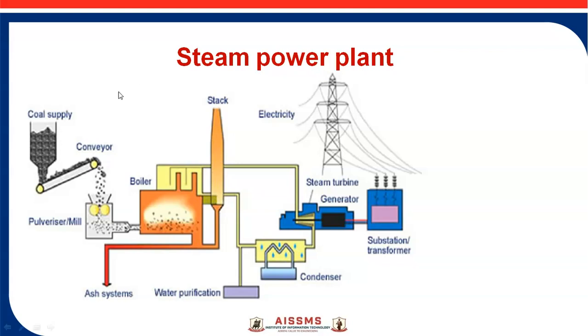Then the furnace. The heated air from the air preheater is supplied to the furnace, and fuel is burned, and the products of combustion of fuel and air are called flue gases. And the economizer: the feed water, before being supplied to the water tubes, is heated with the help of the flue gases, and it reduces the energy needed for the formation of steam.